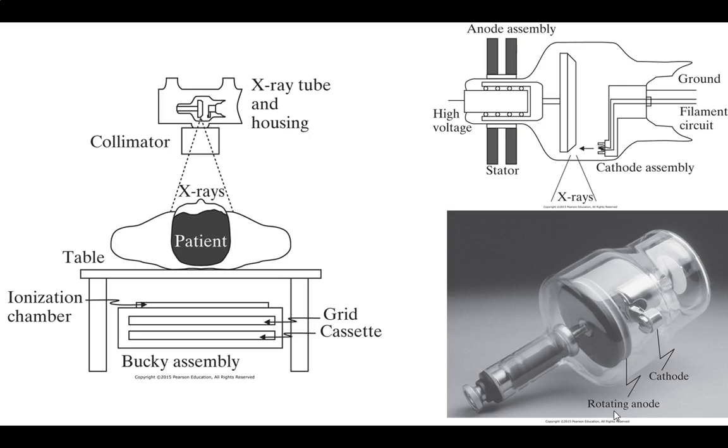The actual exposable part, which will usually be some type of metal oxide, is going to be reactive in the range we're interested in, say some chromium dioxide or something of that sort. When you get that, it's really thin. So remember, our amount of dose depends on how thick your layer is. A very important factor for us, and we'll cover this more when we get to it, is how do we actually make sure we make that bright enough?